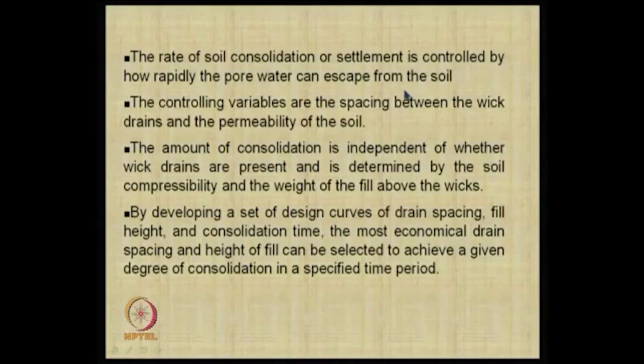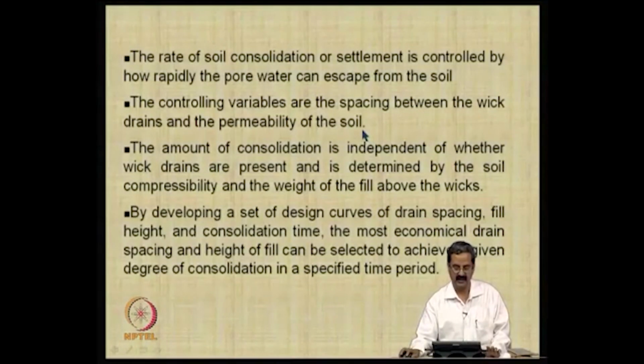So it is a very simple technique, and one can effectively use that, and we will see how it can be done in the field. Essentially, as just mentioned, the rate of consolidation and the settlement is controlled by how rapidly the pore pressure can escape from the soil. So the spacing and the permeability of the soil are the important variables.